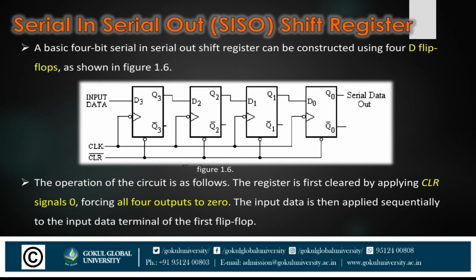Now the serial in serial out shift register, which we also call SISO. A basic 4-bit serial in serial out shift register can be constructed using four D flip-flops, shown in the figure. Here you see the serial output data.